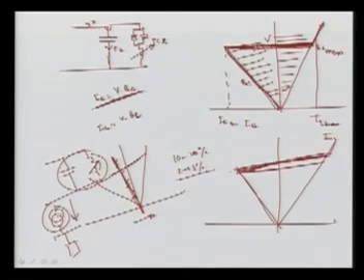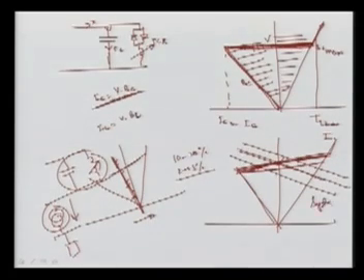To understand this, it is very easy: we can have the different load lines here. If the load increases or decreases and the voltage is less, then the operating characteristic will be here, otherwise it will be here. If your loading is decreased, then we can go for another, and then reactive power support is required. So these are all the system voltage or load lines, and these are called the natural characteristic. So we can have the natural characteristic here, that is the intersection of this.